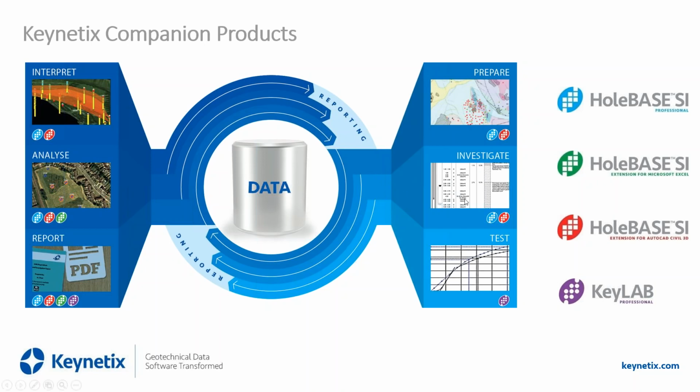You can obviously use the data in our software to generate a boring log, a proper boring log. Click the button, and up pops a boring log, what geotechnical engineers and geologists all use. It does all that as well. But if you've got the data, imagine you've got lab tests to do. You want to find out what the moisture content levels, plasticity limits, etc., are of your materials that you're finding down the ground. Within Holebase, you can schedule those lab tests and send them out to the lab. We actually do lab management software as well, and pull those results back into your central data.